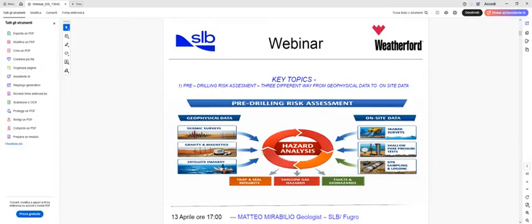When we are talking about the pre-drilling risk assessment, we are talking about the consequence of acquiring different types of data and evaluating the effect of drilling in the area. For example, we make seismic surveys, gravimetric and magnetic surveys using satellite or derived bathymetric images like this. On-site data like seabed survey with the ROV, and evaluation on-site, for example, the shallow pore pressure test and site sampling.